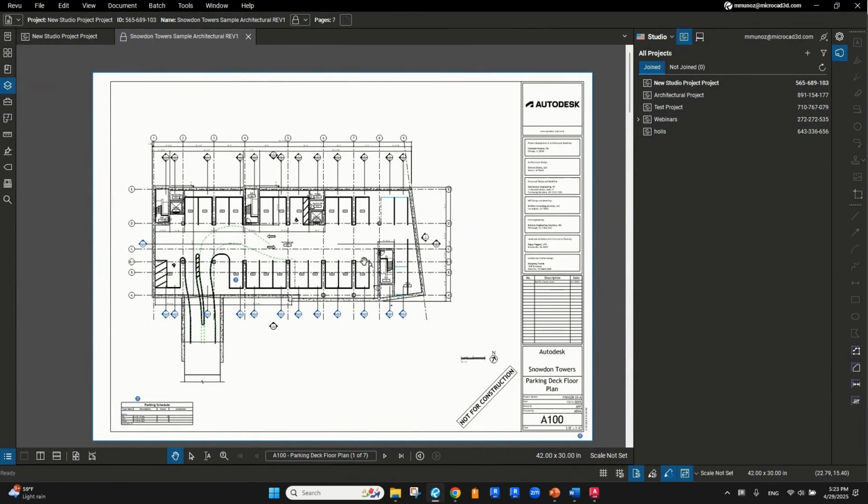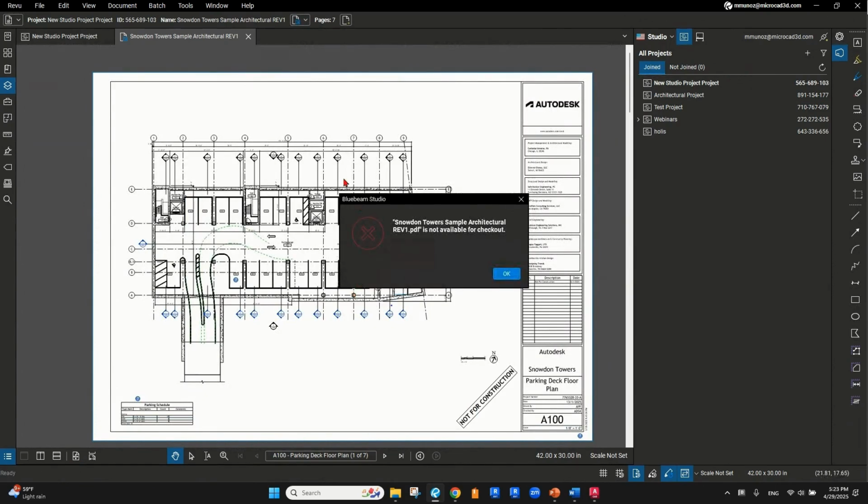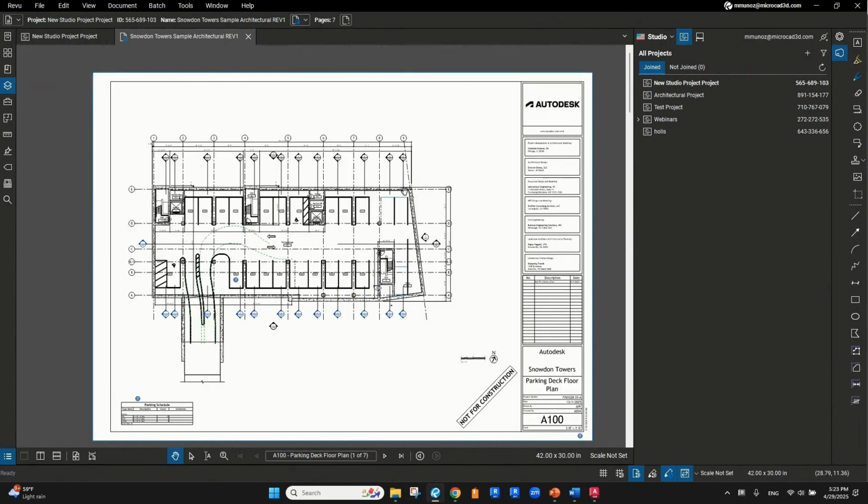We just have to go all the way up on our screen, over here in the middle, and as you can see, there's a lock icon as well. If we click the drop-down arrow, we will be able to see this Check Out option. If we check out a PDF file, we're going to be able to start modifying, commenting on, or marking up our PDFs. And this will prevent our team from making changes to the same file because we have it open. As you can see on the right side of my screen, all the markups are now active and ready to be used.